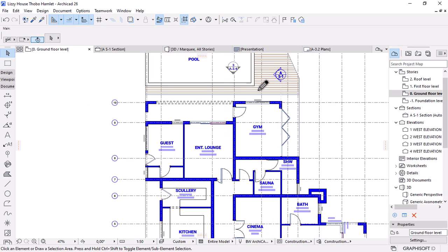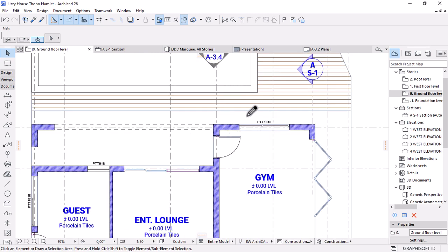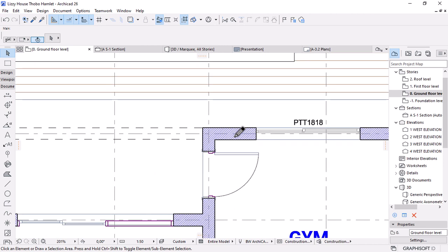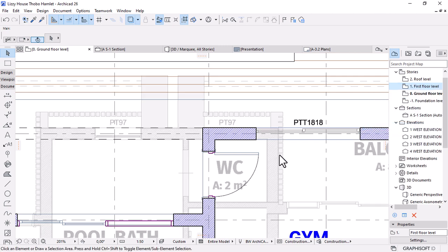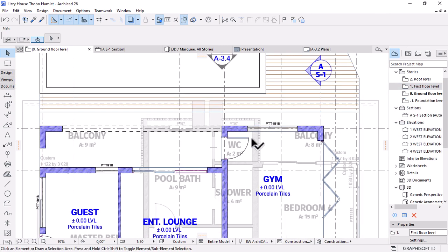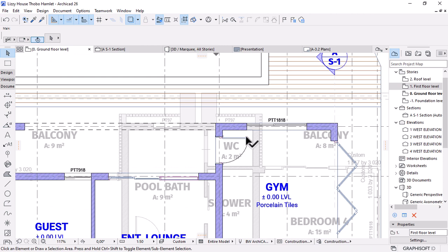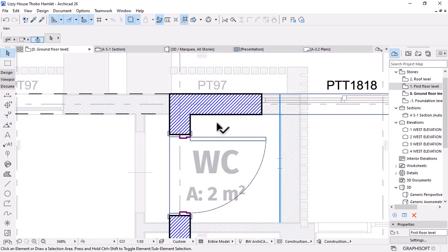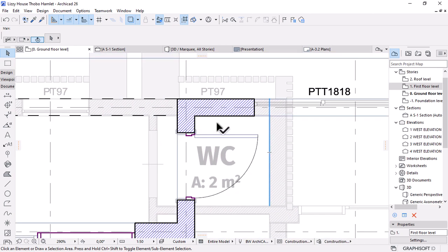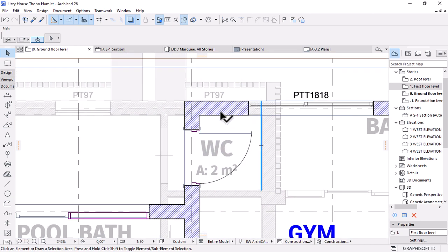Perfect. I'm going to have another gutter here, a duct here, because if you look at, let's right click on the first floor and show as a trace reference. The architect who designed the layout didn't make a provision for the ducts, or ducts for the sanitary pipes and the rainwater pipe. So I'm trying by all means to cater for that in terms of this concept.